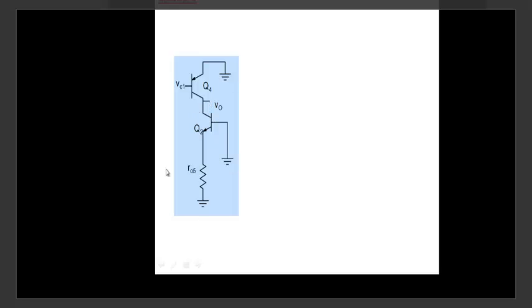And note that all this lower half, there is no source applied here. If you see a block of circuit and you see that there is no independent source applied anywhere, under small signal condition it is all a resistor. The whole thing is a resistor. So this is nothing but a common emitter amplifier with a PNP transistor here, with a voltage applied at the base, and all this is acting as a load.